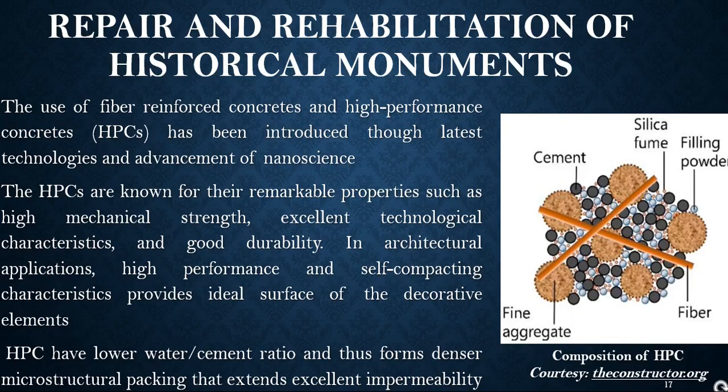As commonly known, high performance concrete is formed by lowering the water cement ratio, and thus it forms a denser microstructural package, and hence it improves the impermeability of concrete and also improves the mechanical strength.